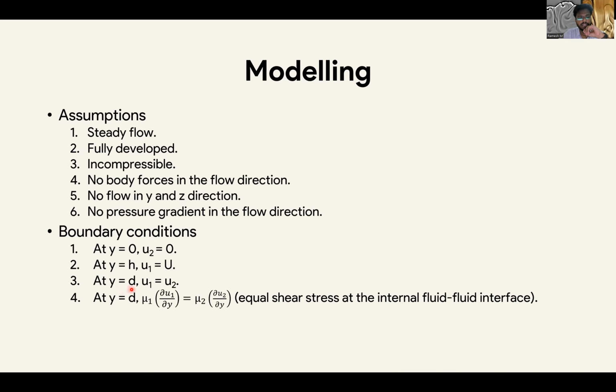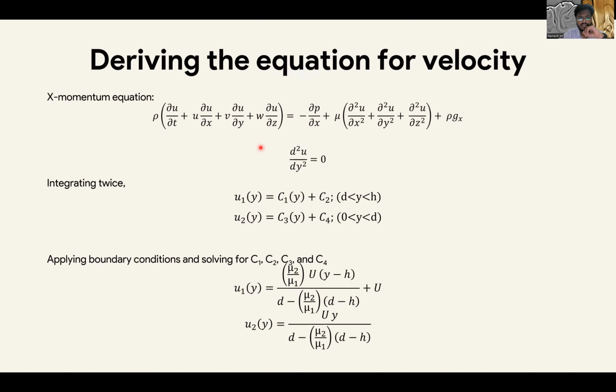And at y equal to d, where d is the distance from the base plate to the fluid one's width, both the velocities will be the same. So fluid one and fluid two's velocity will be the same. And at y equal to d, the shear stress will also be the same. So we take these boundary conditions. It is also similar to the previous problem.